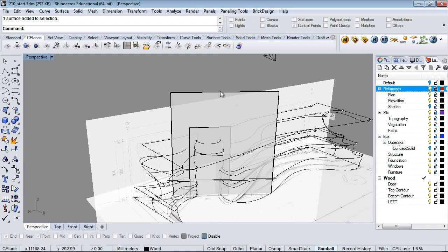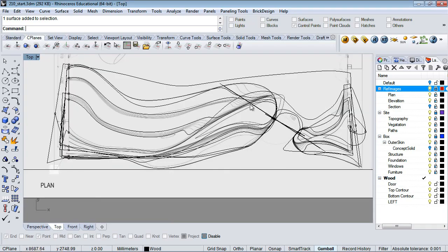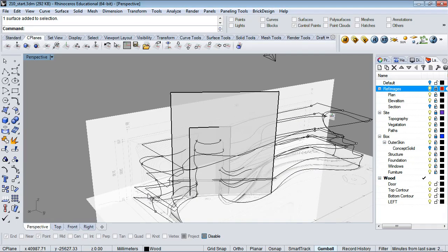You just move around, and I get it set in plan view. Okay, in the top view, I get them set, and then I move into the perspective, tell it to orient the construction plane, and then I draw in perspective. Okay, and turn off your object snaps when you're doing that, and just snap to the intersections. That way you can really control what it's going to look like in section, and you have a conception of the overall form.